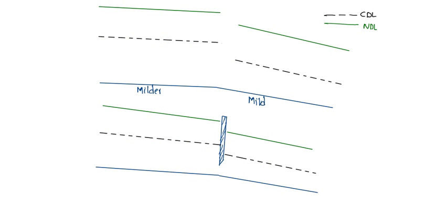Critical depth at reach A is 0.623 and normal depth is at 1.2 meters, whereas in reach B, say this is A and this is B, critical depth is indicated by dotted line and normal depth by green thick line. Critical depth is at 0.48 meters and normal depth is at 0.918 meters. Here is the control point.